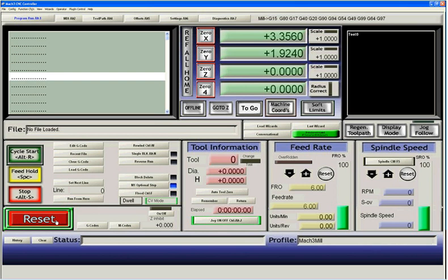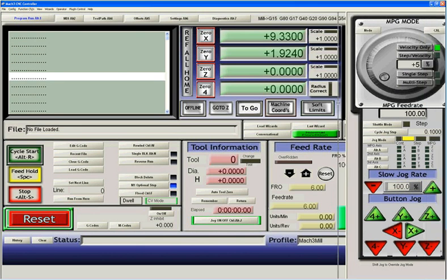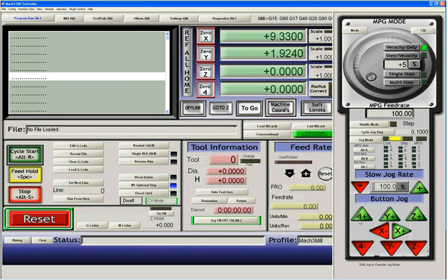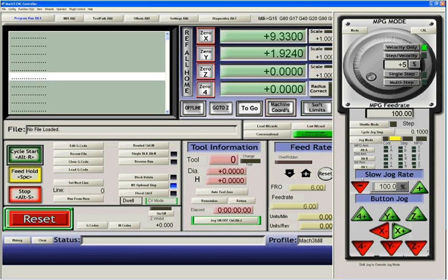Now a secondary complaint is, okay, my motors move, but they move very slowly when I jog. Why would that be? Well, as you can see, if I hit jog, I'm going at 120 millimeters per minute on this system. If I hit the tab key to bring out the jog tab, and incidentally, to control the jog tab, drag it out so that it is on your system facing you and you can read it fully, tab it in, tab it back out, and it will remember its location from then on. The jog rate down here at the bottom, you can see it's set to 100% on mine. That can be set to any value, so make sure that it's set to a value that you want it to be for your slow jog.